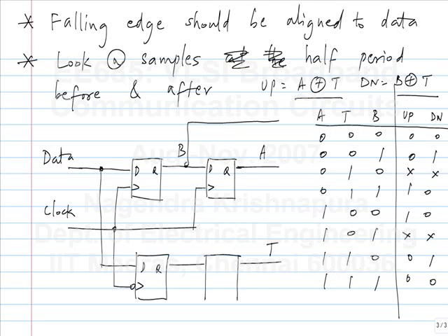So again, we are talking about high speed, so if you want to economize the implementation as much as possible, you don't use a full flip-flop, you just use a latch. You can use a positive edge triggered flip-flop. What happens is then you will have positive latch, negative latch, positive latch, negative latch, negative latch, positive latch. So effectively you are combining these two to get a single latch. That's all. I think we did this once before when we did deserializers or something.